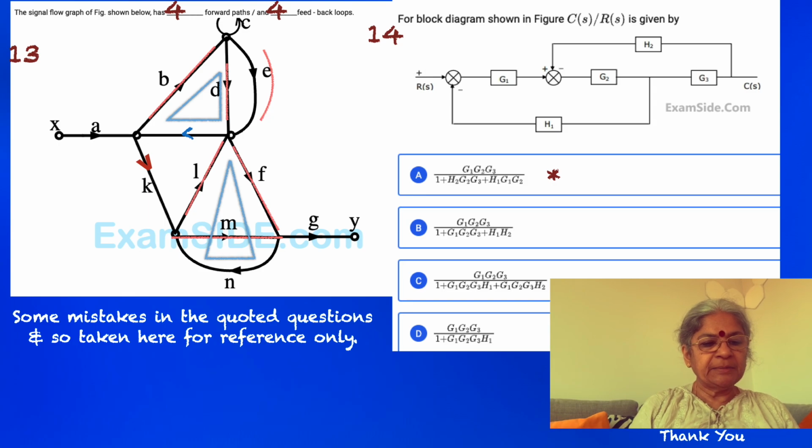And the K had no arrow, so I have put an arrow there to show that it's feed forward. So now let's start collecting the feed forward paths. A, B, E, F, G is obvious. Again, it has been marked out. That's that. But you are supposed to pick up in the examination context. A, B, D, F, G immediately comes through. Let's go via K.